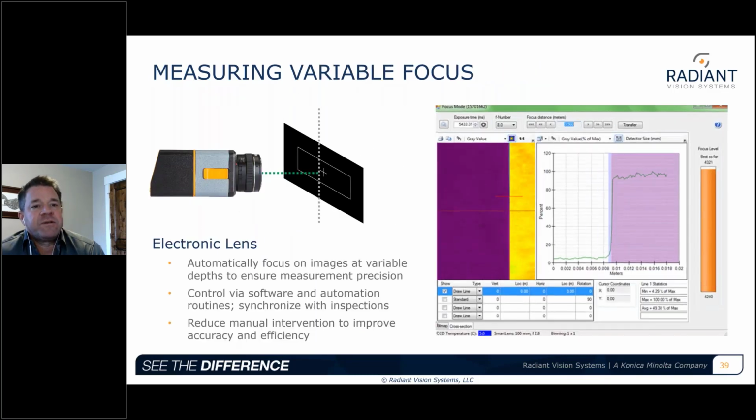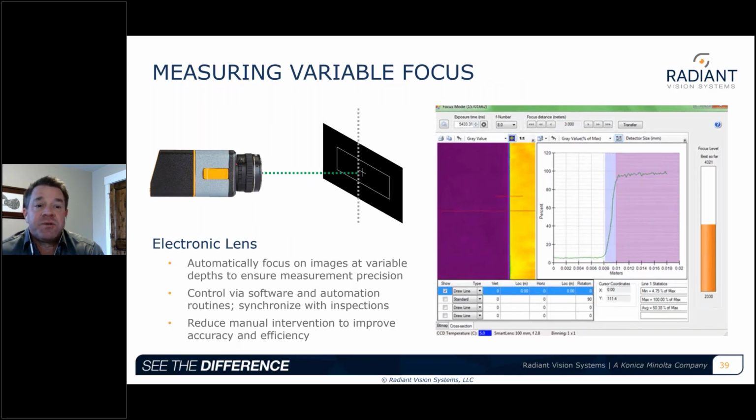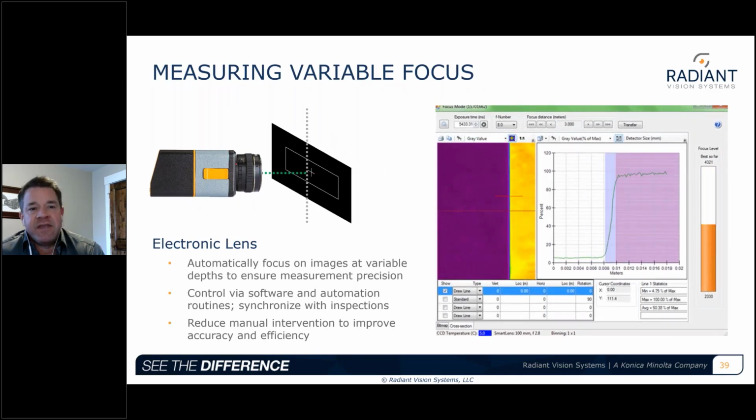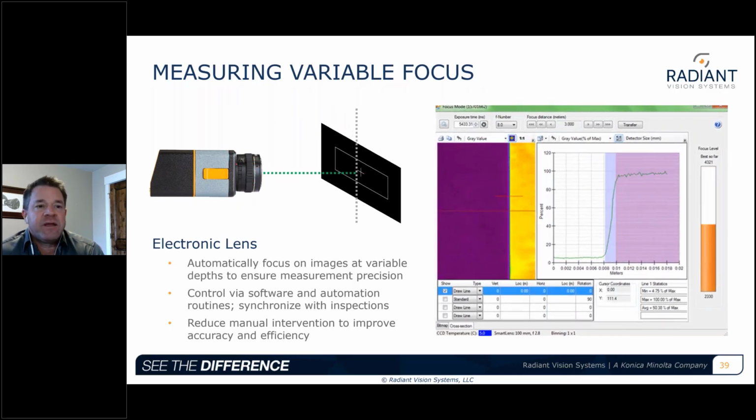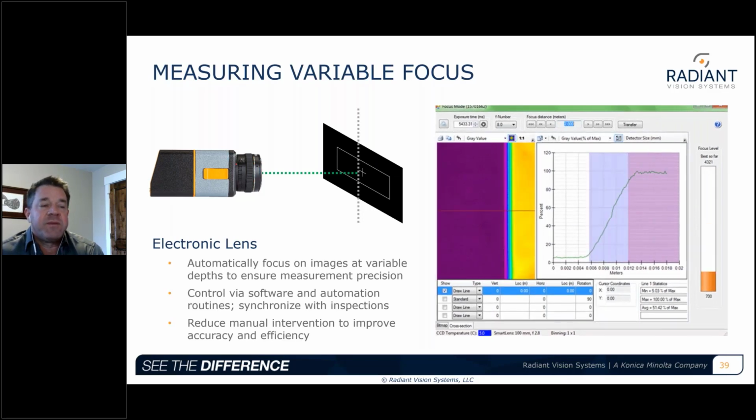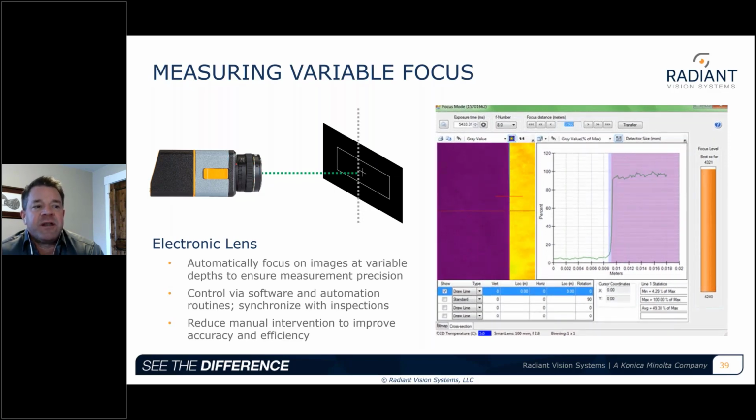To account for focus again, the measurement system should respond like the human eye. Like the eye, an imaging system's focal point can adjust to meet the depth of perceived virtual objects. However, images projected at two or more focal points demand more from the measurement system's optics than just a fixed focus lens. Radiant has chosen to apply electronic lenses for our systems, which are controlled by software to optimize focus and aperture settings for precise imaging depths.